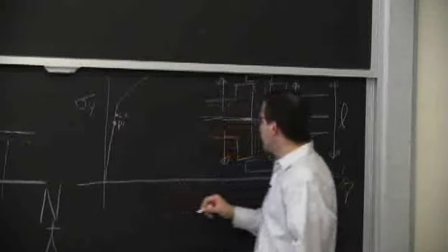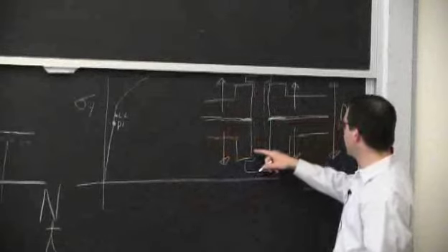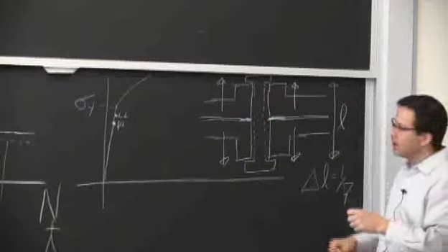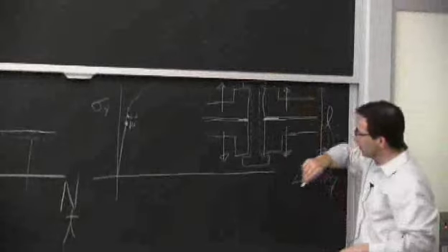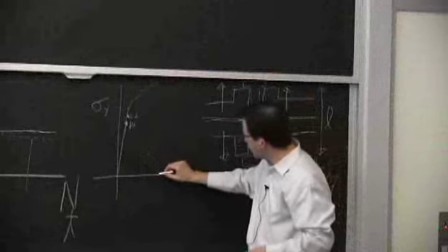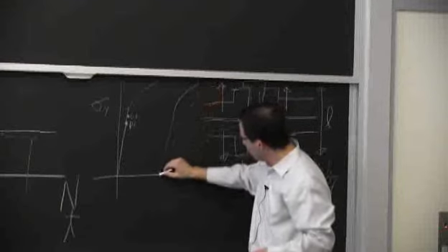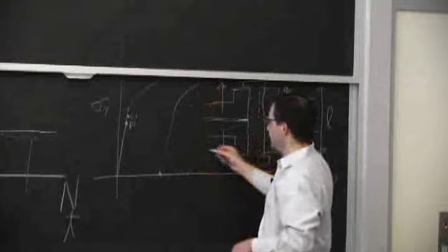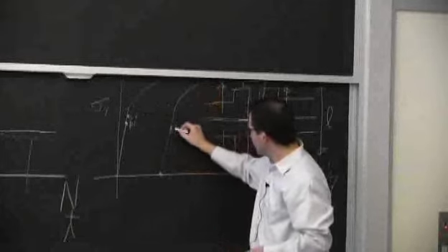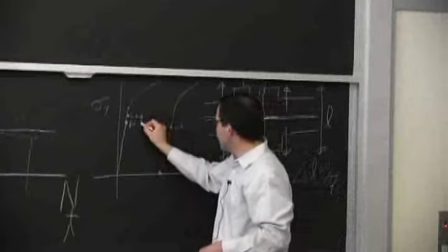Okay. If we did not have our contact here to make this a rigid block, just the bolt being pulled, then you'll start on another stress strain curve. So I'll make another one here. You start from 0, and it's 7 times this difference. So you go to 70% with the live load. Now, you can start seeing that as far as amplitude,